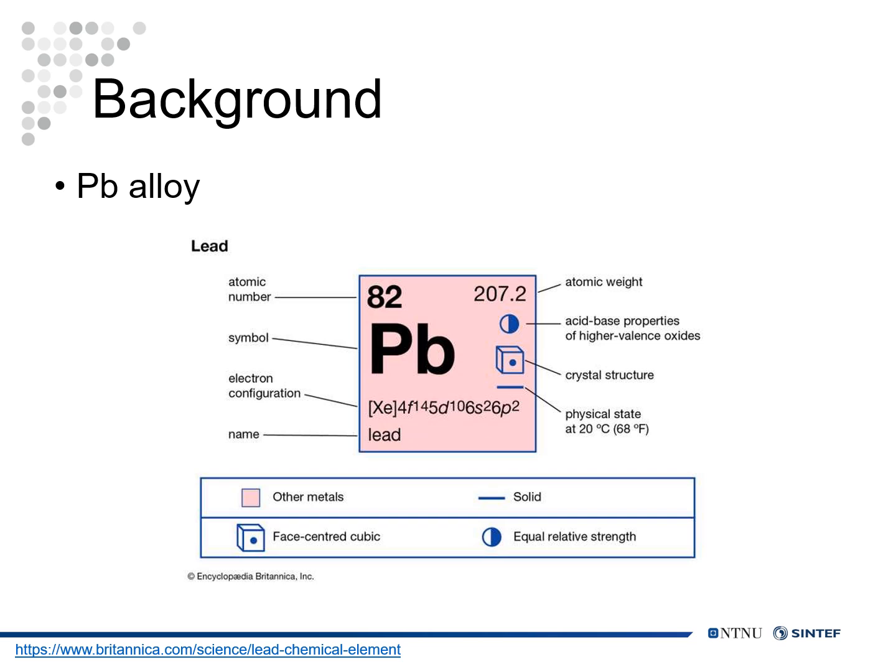A common understanding of this material is that it has a relatively low melting point, around 600 Kelvin or about 327 degrees C. This relatively low value causes a lot of strange behaviors such as relaxation, recovery, recrystallization, and even creep already at room temperature in lead, in contrast to most conventional metallic materials which will experience these mechanisms only at high temperatures.